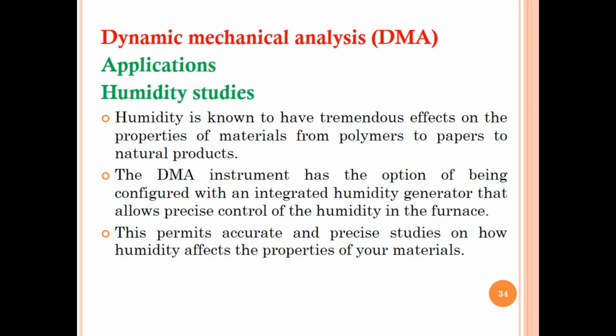This is another application: humidity studies. You can study different types of polymers and materials under different humidity conditions. Humidity controllers are placed in different DMA machines to control the humidity.